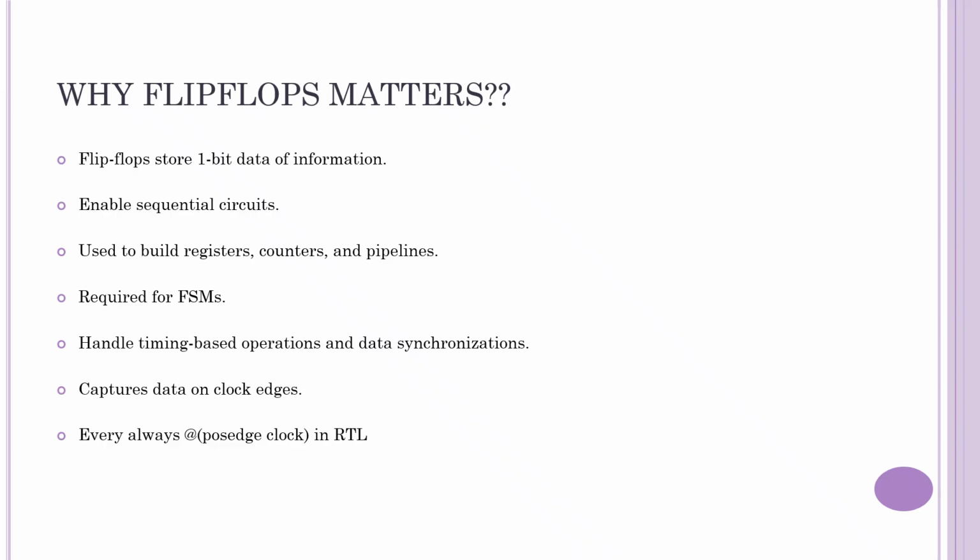Sixth, in RTL, every always @(posedge clk) means a flip-flop. If you are writing Verilog or SystemVerilog like always @(posedge clk), congratulations, you just described a flip-flop in hardware. The synthesis tool doesn't see the code. It sees hardware, and that hardware is a flip-flop.